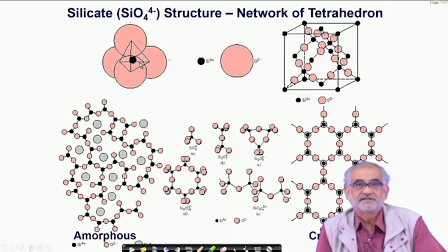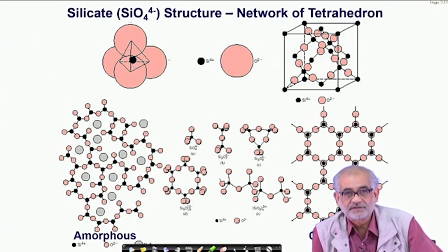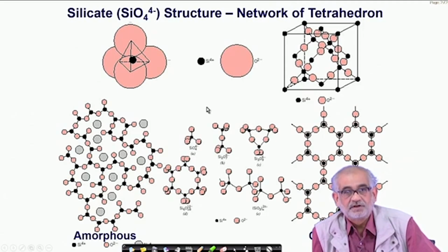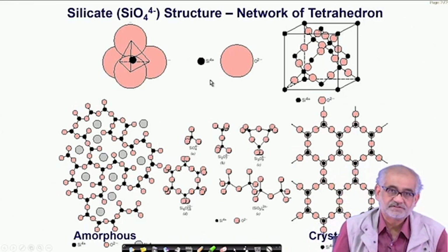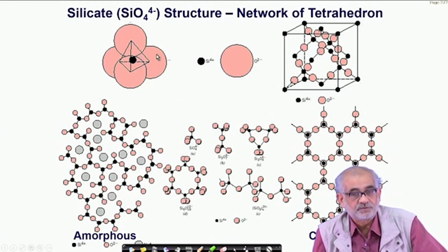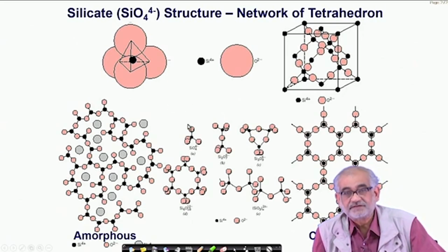So here is an interesting development: the same solid, the same chemistry, the same bonding can manifest both as crystalline and non-crystalline. So when we talk of the structure of solids and the properties of solids, we have to be aware of not only the structure but also various possibilities of structural manifestation. And this is dictated by thermodynamic terms. To be more precise, something called the Gibbs energy, which is derived from the intrinsic property of specific heat, showing up in the form of enthalpy and entropy, and the relative contributions of enthalpy and entropy decide the relative Gibbs energy of a particular phase in a given system. And depending on the relative Gibbs energy, and to be more precise, the chemical potential, one decides whether a particular phase is going to be stable or not. And structure does play a role in determining such stability.